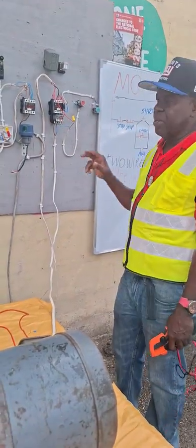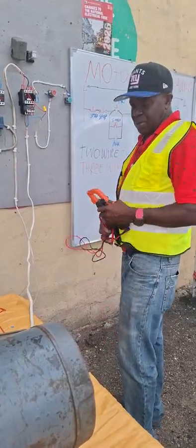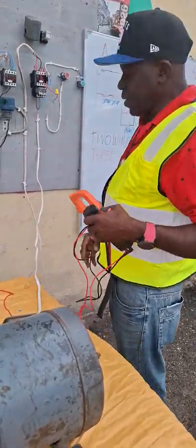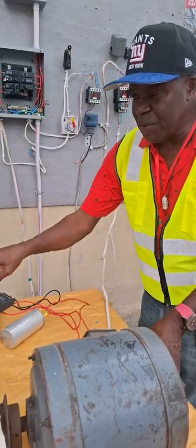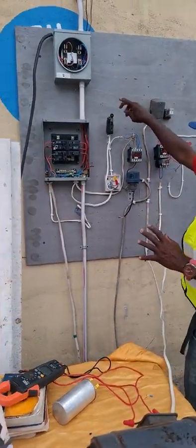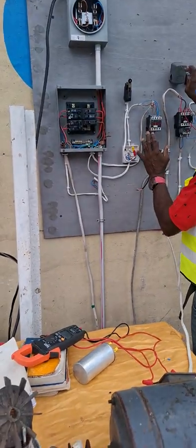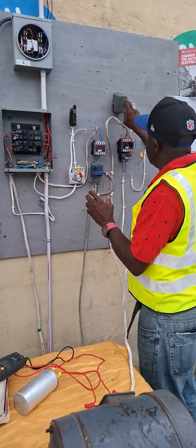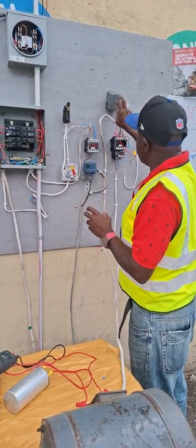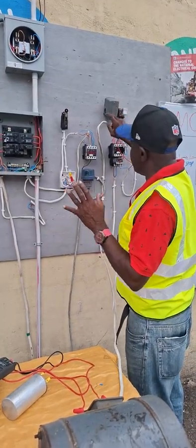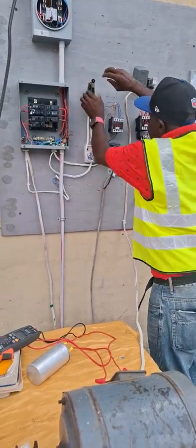I don't incorporate an isolator in the circuit today. Right, but he's divided, right? So I'm now just going to start off with my single phase motor here, right? And this is going to be my input, my pilot device, my limit switch. This is also an input device, it's a pressure switch, but it's not connected to the pump right now, so it couldn't operate the motor. So I just incorporate this to get it going.